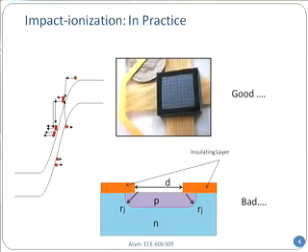Now a single photon comes in. That's the seed. The single photon comes in and generates an electron-hole pair. And now you have an electron which is falling down this huge potential, and similarly a hole falling down, from the top of a mountain going down the hill. And in that case, you can have single photon detectors based on this avalanche process.